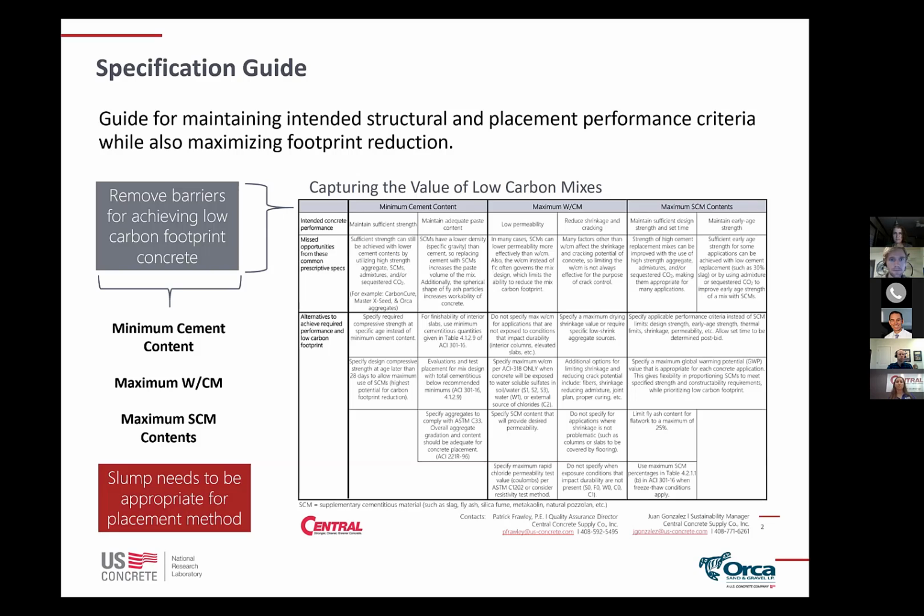What it pretty much goes through is three primary things that we tend to see that are prescriptive in nature: minimum cement content, maximum water cement ratio, and maximum SCM content. It shows what we believe the intended performance usually is by specifying those, and then provides suggestions for alternate ways to still achieve that performance, but be more performance-based rather than prescriptive-based in nature.